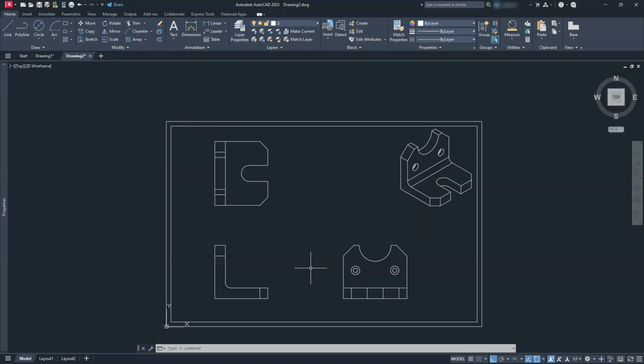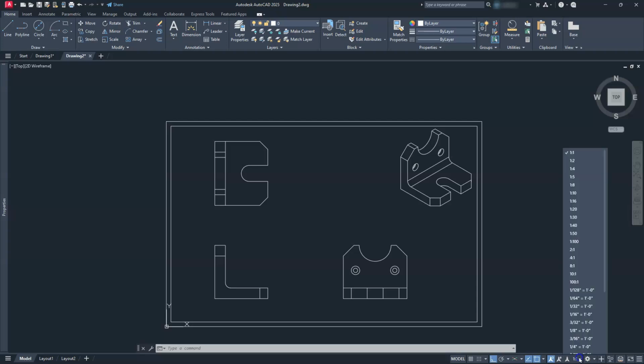Next, we need to figure out what our scale factor is, right? We already typed in 35 as my scale factor. Do I want to keep it at 35? Well, in this case, it does look like everything will fit on here. And so I have to decide, am I going to use the annotation scale, which is sitting here, or am I going to use the standard method of doing things? I think in a lot of my other videos, I used to go ahead and do the annotation one. This one, I'm going to use the standard option.